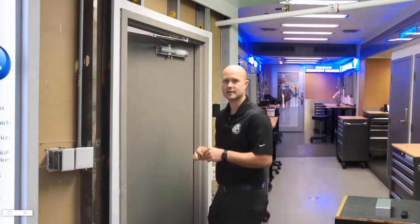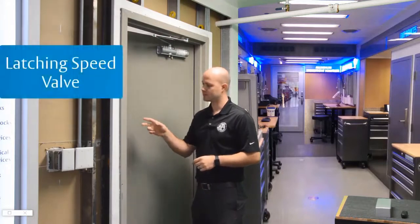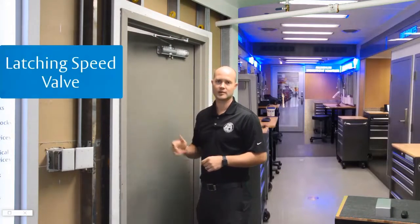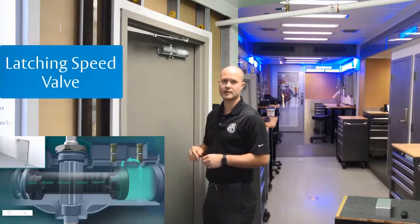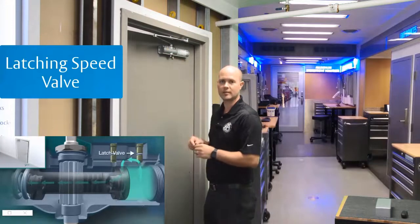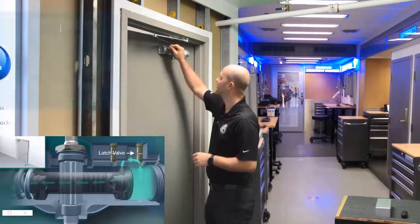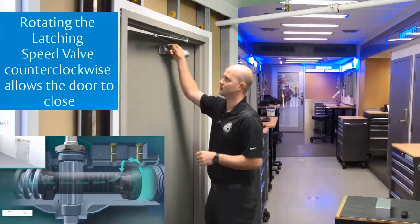Now notice that the door closed to a certain point. Well, this last few degrees of our closing is our latch position. The door will not close as long as our latch valve is screwed in. So we need to back our latch valve out to allow our door to finish closing.